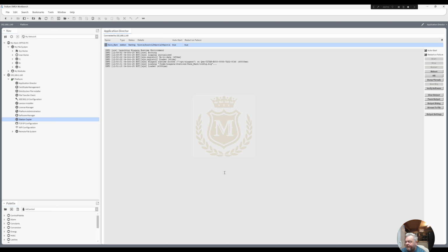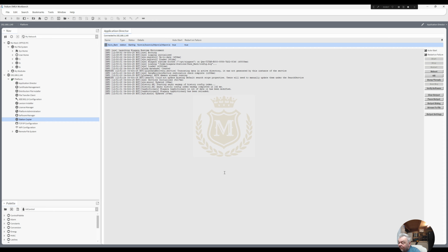So they've done a backup, they've got a .dist file, and you've unzipped that .dist file, so you changed it, instead of dist at the end, you change it to zip, and then you've unzipped it, took the station file out of it, put it on your PC, and then you've had to change the passphrase and add a user to it so that you can actually work or load it onto a station to work with it. You can work with it without loading it onto a station, but it's better to load it onto a spare Jace so you've got that there.